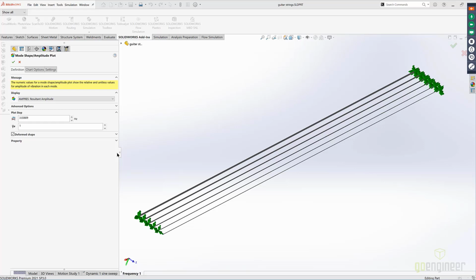The limitation of Simulation Pro is in dynamic elasticity kinds of analyses. After a certain point, the material can yield really weird results, but if you change your deformation scale to true scale and you turn off the large displacement flag, you can get pretty accurate results, enough to at least proceed on with your analysis.